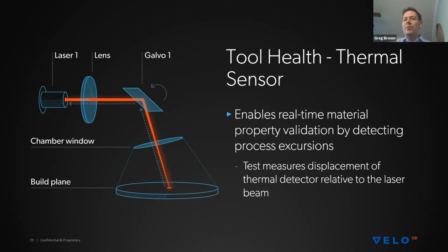That's the incoming laser path that's then hitting the build area. But at that build area, you're making a melt pool, which could be 1,000 degrees or more, and you're getting a lot of thermal emission from that melt pool. And a lot of that light is basically traveling back up the same path, and we can pick it off and send it over to a detector.